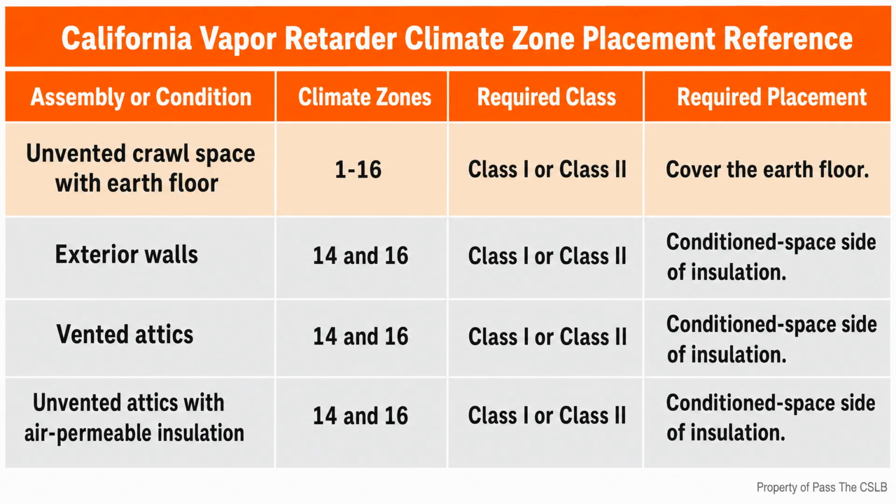Single-member window and door headers receive special attention in the quality installation criteria. For 2x4 framing, the header needs at least an R3 insulation layer. For other assemblies, the minimum is R5. That insulation is placed between the interior face of the header and the inside surface of the interior wall finish. The number belongs to the framing condition, so I remember the pair as smaller framing R3 and other assemblies R5.